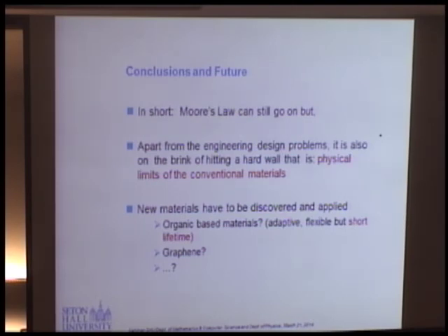Now silicon has reached its mobility limits. Even if you put in more arsenic, you're not going to increase the performance of the computer. Germanium, silicon germanium, has a higher mobility. Even if you don't increase the number of carriers, the mobility is increasing. So this is why people are going to go back to germanium. That's in the next 15 years.